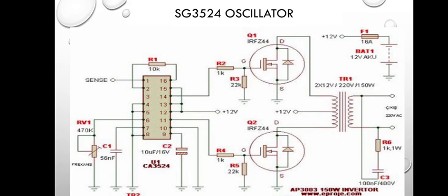That is for testing. So this pin 10, once there is an analog signal of up to 5 volt, let it not be more than 5 volt, please. Any signal coming to this pin 10, so long as it is not more than 5 volt and not less than 3 volt. Now once this signal is connected to pin 10, automatically the IC will pause. The pause means it will shut down. The switch and everything is connected, but the IC will stop oscillating. The oscillator will stop. Every other thing is okay, but immediately the 5 volt is disconnected, the oscillation will continue.